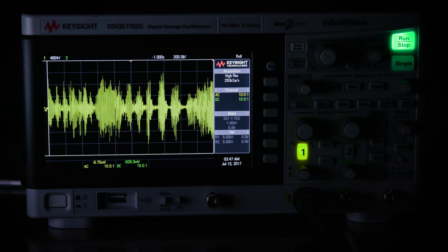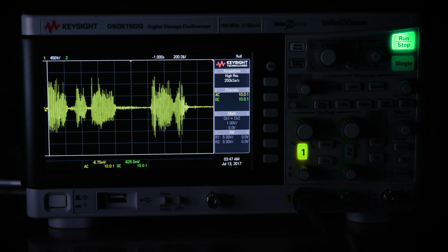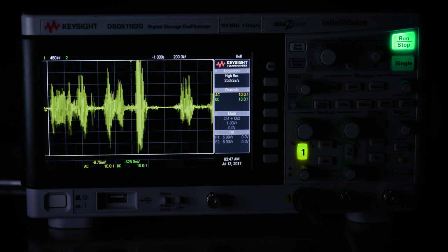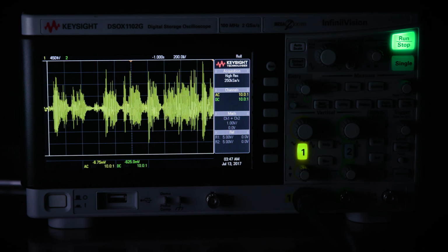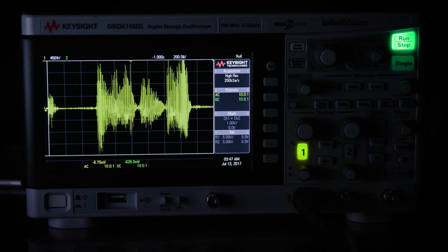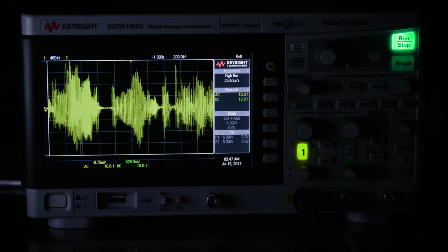At the simplest level, it's a switch, but then we have to talk about the inter-symbol interference, how to keep the sample that you're going to take in A to D converter A different than in A to D converter B. If you had an infinitely fast switch, that would do that, but you don't have an infinitely fast switch.